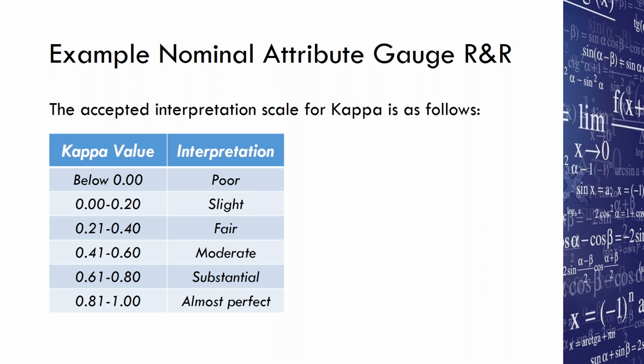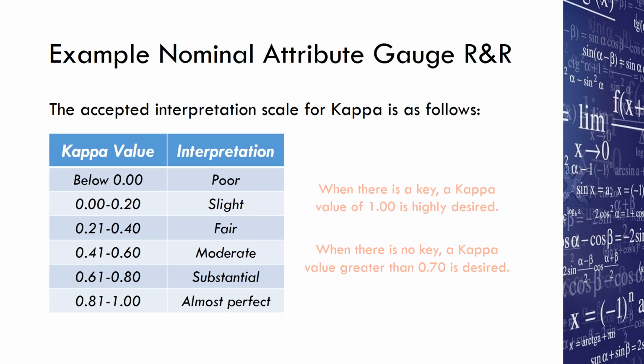If we had missed a single one at that plant that was installed incorrectly, we would have had to have a campaign on the entire lot of vehicles. Instead, we used a medical borescope that we were able to stick inside of the latch of each door. That medical borescope was able to tell us exactly whether that rubber bumper was installed right side up or upside down. And we got a kappa value on that attribute agreement analysis of 1.0.